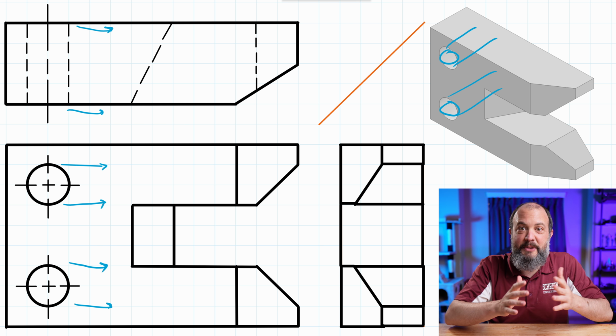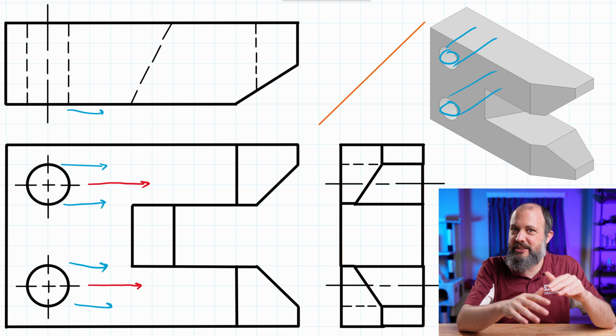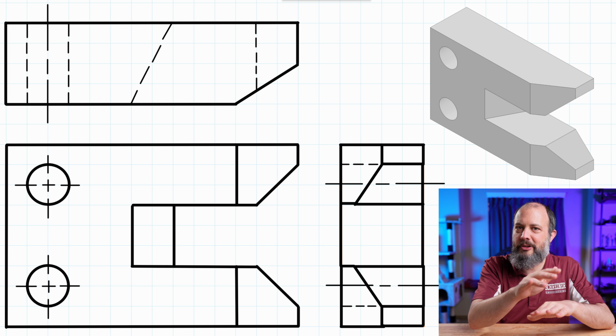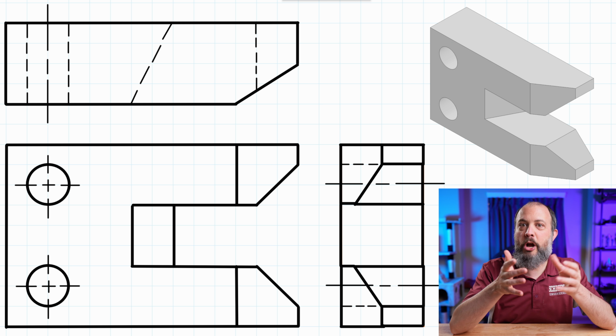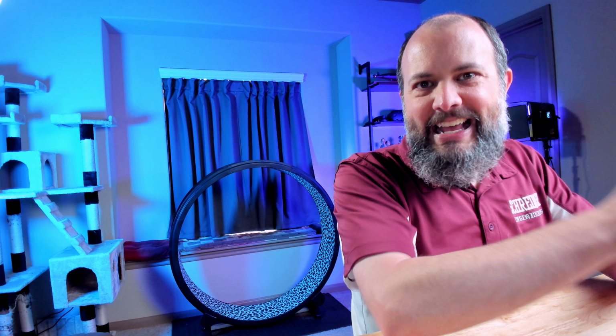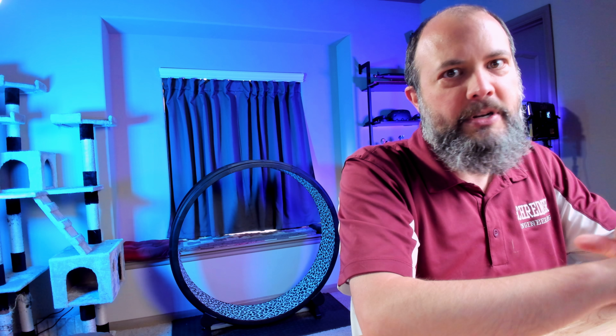And last things will be some dashed hidden lines to represent the holes. You won't have to actually draw very much because most of the top and bottom of the hole actually lines up with existing solid lines, and visible lines have priority. So whenever a visible and a hidden line should be drawn at the same place, you just draw the visible line, not the hidden line.